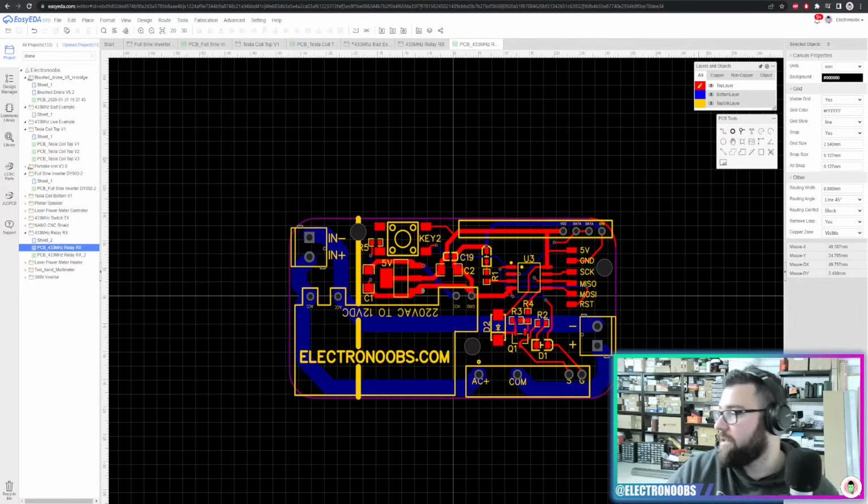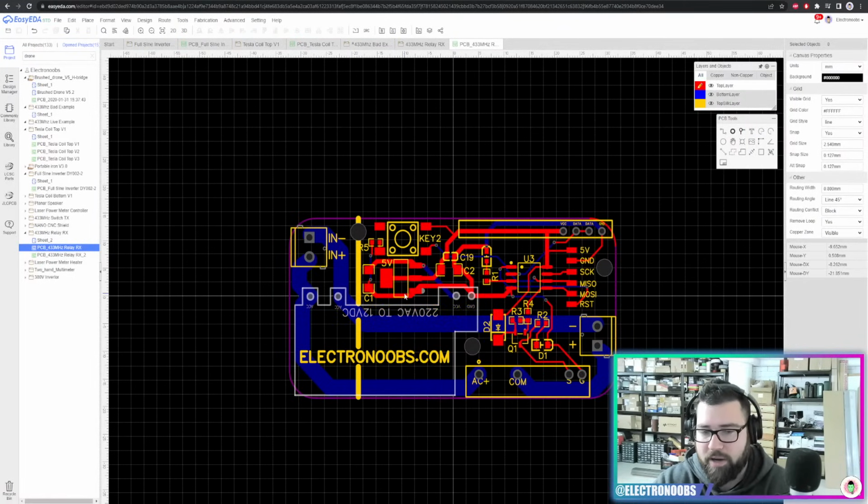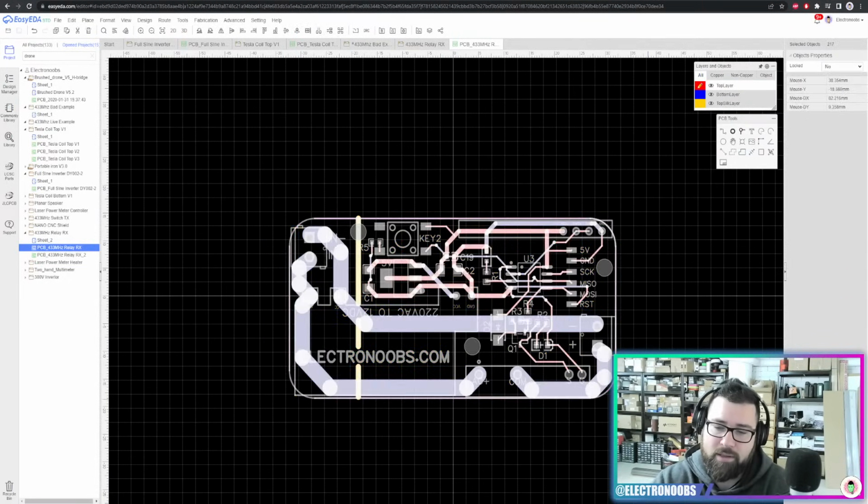The HV doesn't seem as insulated with such long HV tracks. Yes, that's also true. I mean, it's better to have insulation over the entire board, but not all the pads, compared with not insulated tracks all the way. It is a lot more dangerous. I understand that.